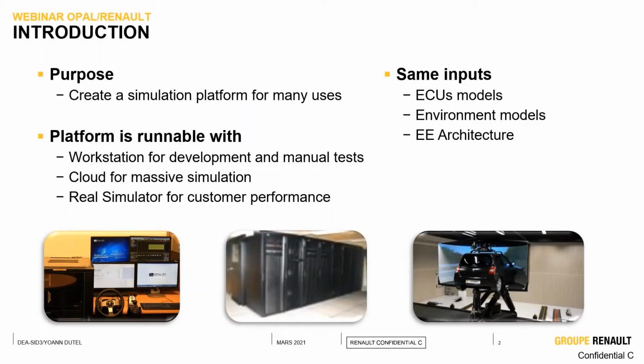One of them is a workstation for development and manual test. Another one is the cloud for massive simulation and massive use case validation. And the last one is the real simulator to have the driver in the loop and check customer performance. All of these environments use the same inputs, like ECU models, environment models, or the electrical and electronic architectures of the car.